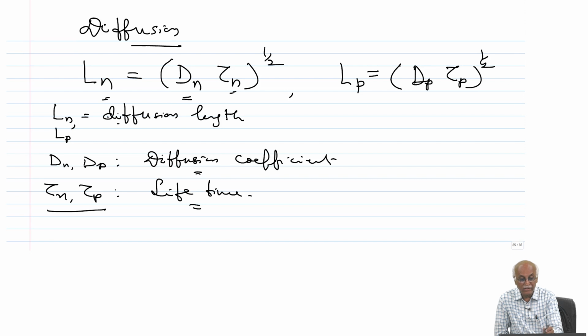So, if the diffusion length is 1.5 micrometer, and if I have an intrinsic layer which is 3 micrometer, I am sure that the electron will not reach its p or n side before, through this intrinsic layer, it may get absorbed. The probability is very large. So, these diffusion length parameters are also useful, and based on material characteristics we can easily determine them.